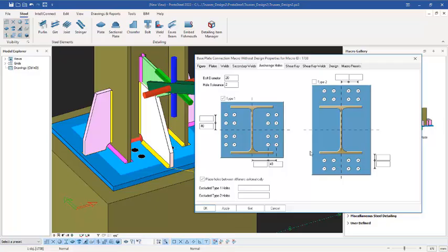So once you have this dialog like this, I will remove this 40 I'm having here, and then I will first have 40 behind here, since I wanted only 2 holes at this first and not 4. So I click on apply now. You can see I'm now having only 1, and the distance from the web to where the hole is located is just 40. So this distance now I can manage it by pushing the hole outward. So for me to do that, I can key in here to be maybe 60.